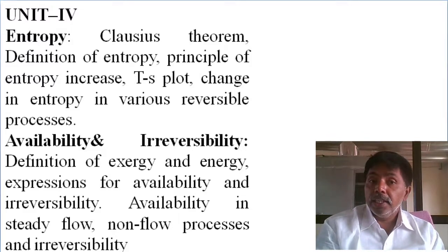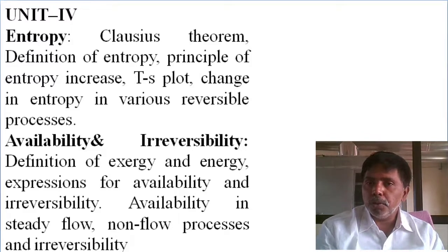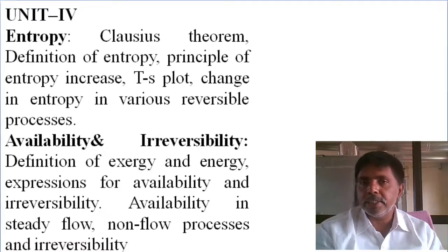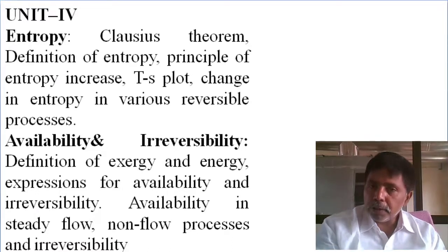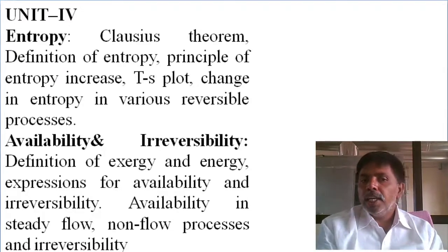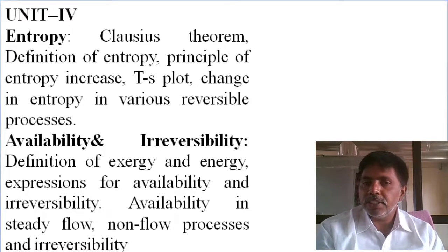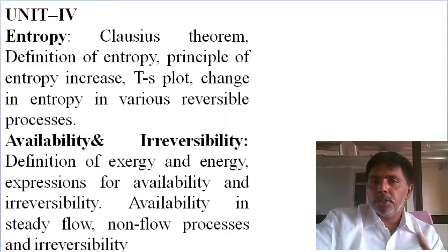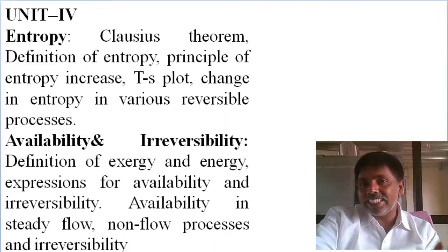Next, availability. Once you determine entropy, multiplied by the dead state temperature, you will get the irreversibility. Total energy minus irreversibility gives you the availability. So: definition of exergy, expression for availability, irreversibility, availability for steady flow and non-steady flow processes. In this unit we are thoroughly discussing directional feasibility.